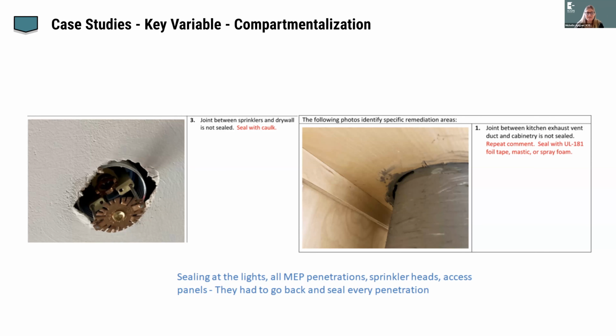and then certainly testing to evaluate unintended leakages, right? This wasn't on purpose. Someone just didn't finish the job, right? It's a team effort. It's not a blame game. It's totally not about that. It's about how we all do our best work together. And air tightness, again, it's kind of everything. Like Mark said, the R values are the R values. The modeling is going to show you the windows that you're using, the exterior assemblies that you're planning for. But if you don't hit the air tightness, it can have wildly different effects on the actual final outcome.